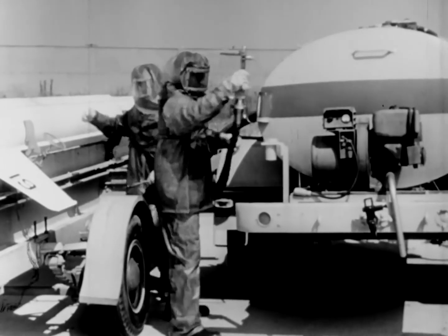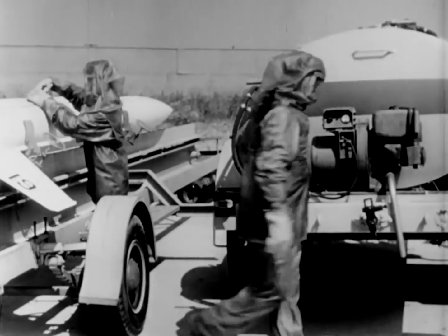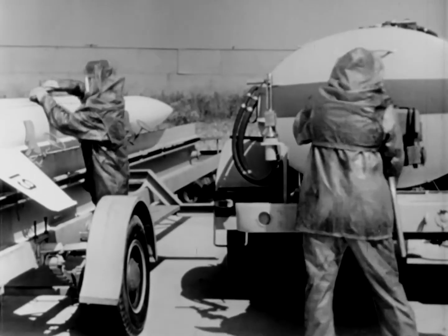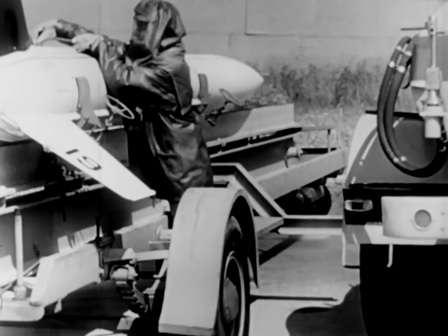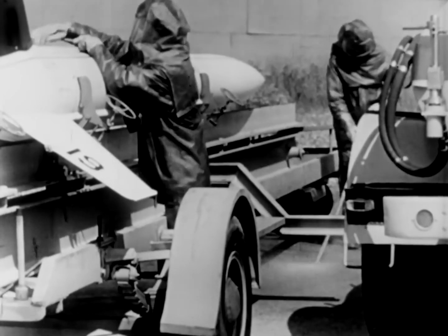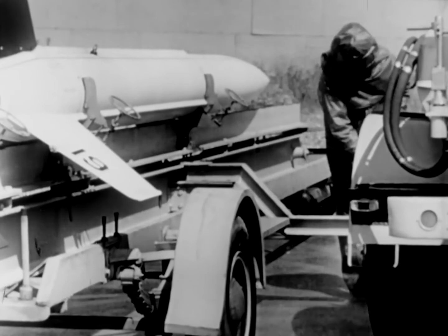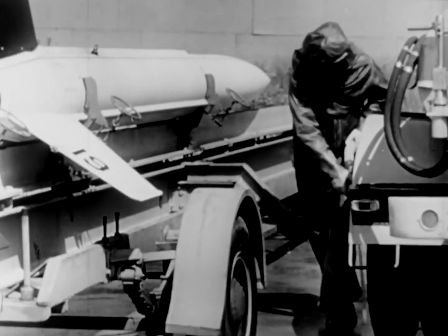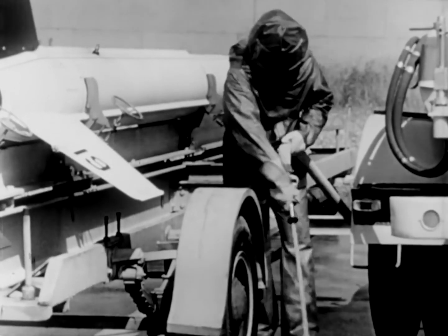Aside from personal precautions, none of these liquids should be handled carelessly. In loading, only one of any two propellants is handled at one time, never both simultaneously. And care must be taken to dispose of any spillage before the next half of the bipropellant team is brought to the rocket motor, so that spillage from the second propellant will not cause combustion during the fueling operation. This is especially true of aniline, which has a very low vapor pressure and will therefore contaminate an area for a long period.